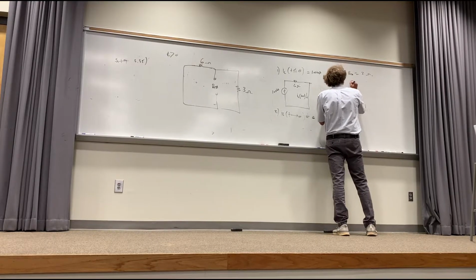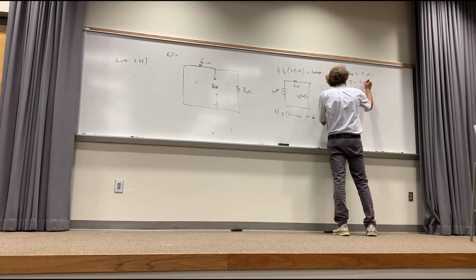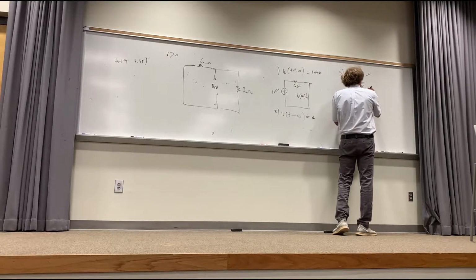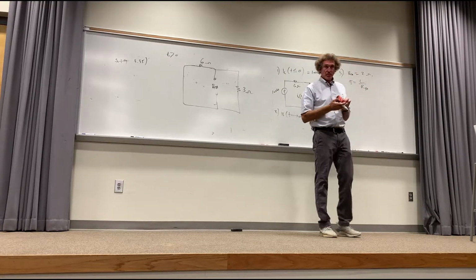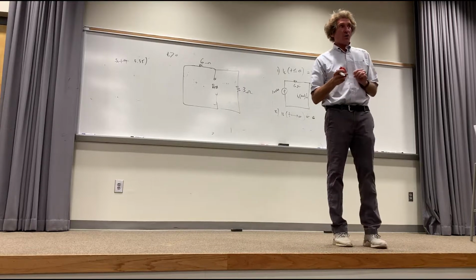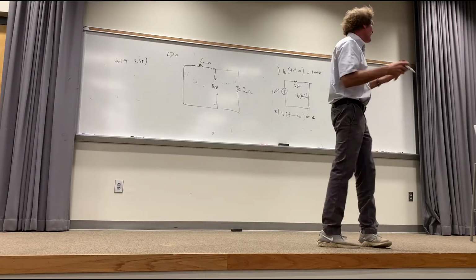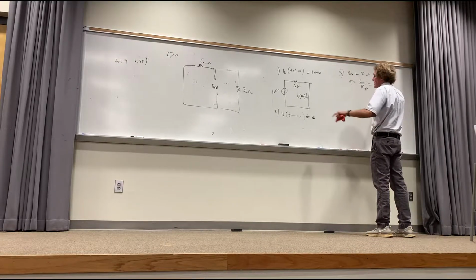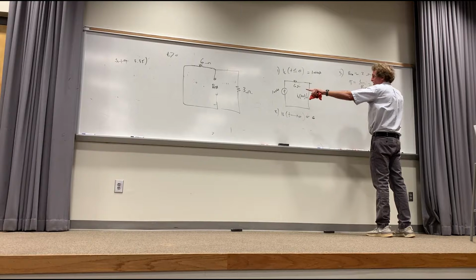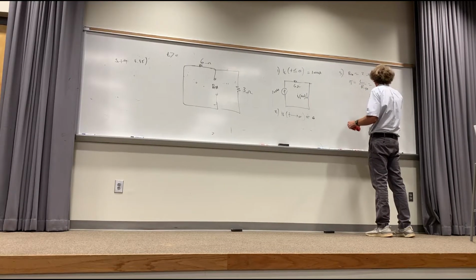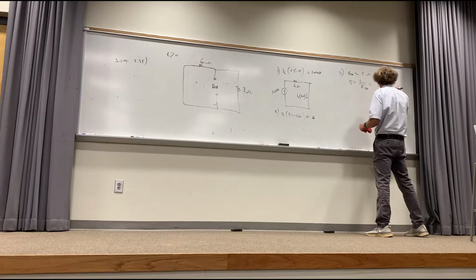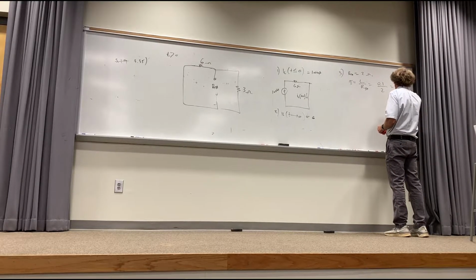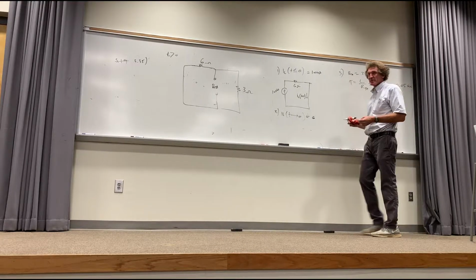And then what is tau? Now this is an LR circuit, it's what? L over R Thevenin, isn't it, class? You remember that? It's R over L. I mean, L over R. And what is that going to be? L is erased. What was it? 0.1 Henrys. 0.1 over 2, right? So that's 0.05 seconds. Agree, class?